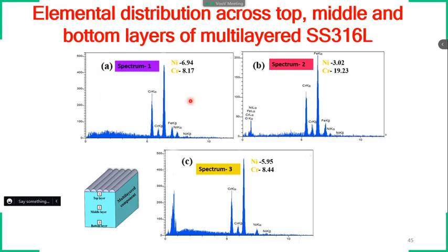But if the ratio is very high, as here in the middle layer, ferrite will tend to preferentially segregate. If ferrite is distributed all over the component, it is fine. If it is preferentially segregated in one zone, it will act as a crack nucleation point. As ferrite is a highly brittle phase, that zone will become very weak and may trigger cracking complications.